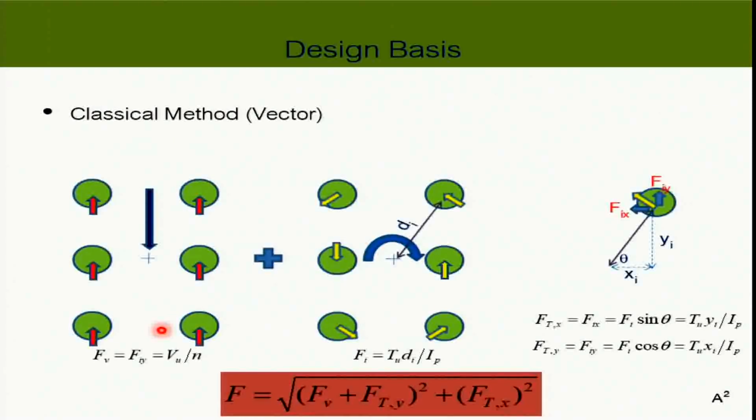Okay? Now, if you use the classical method, it means that you need to move the force to the center of the bolt group, and you have this as the bonus, right? Generally, people would call this moment, but the way it creates a force, the extra force on the bolt, is actually a torsion itself, right? This is torsion because it's going to twist our bolt group.